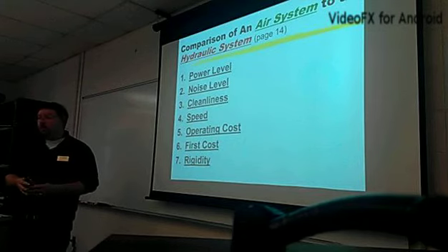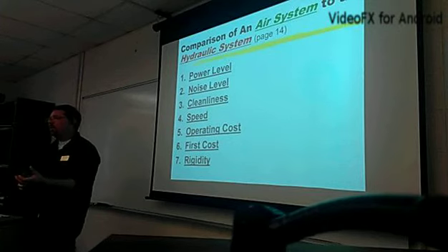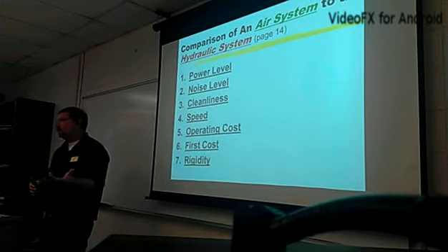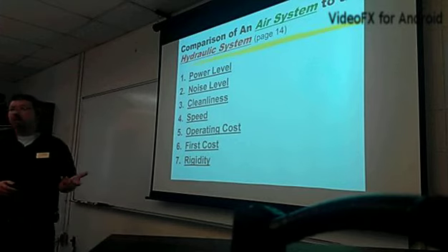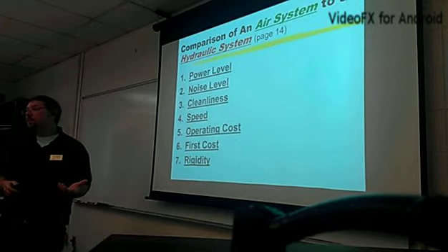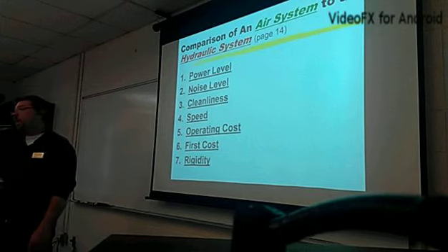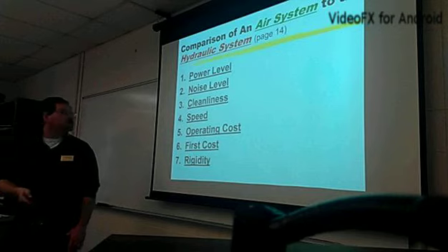But the whole point about the speed deal is you can get by with smaller piping, because compressed air, just by the nature, is going to move faster than oil, right? Because there's not as much resistance to the piping, because it's an air form instead of liquid. Okay? It also says there is an exception when it is an accumulator system. Typically, though, if you want a high-speed kickoff, you would do pneumatics. You wouldn't even think about hydraulics.